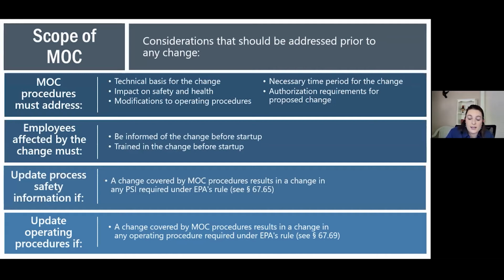Considerations that should be addressed prior to any change. What is the technical basis for the change? What is the impact on safety and health? Do the operating procedures need to be modified? What is the necessary time period to implement this change? Who needs to authorize this change?